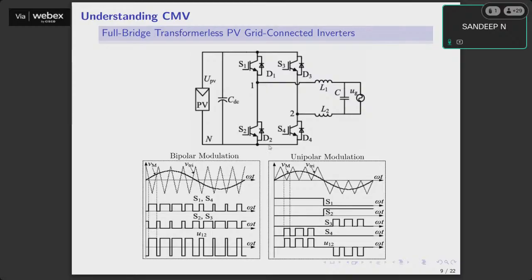So if we are asked what the switching frequency of the inverter is, who decides? It is decided by the carrier frequency: 10 kilohertz, 20 kilohertz, 50 kilohertz. That is what it means. Then you have your V triangle. Then you have your VM corresponding to the modulation signal, which is the fundamental voltage that we are trying to synthesize through this inverter.